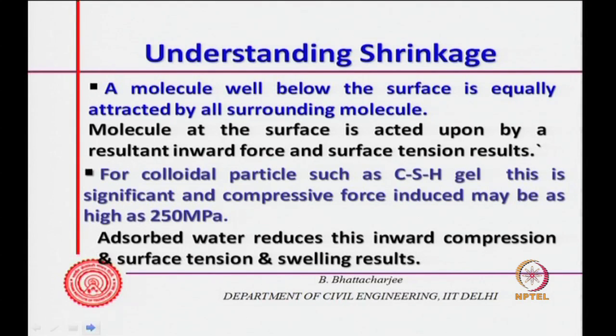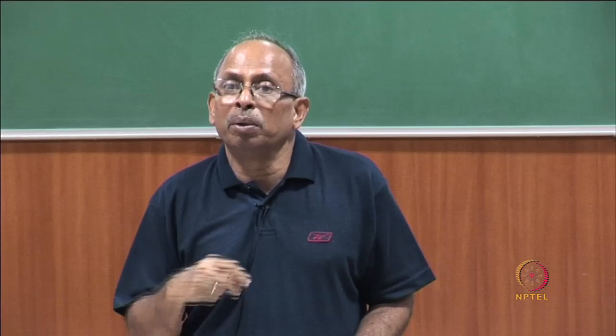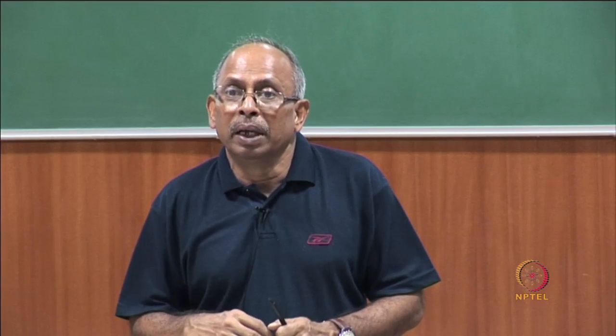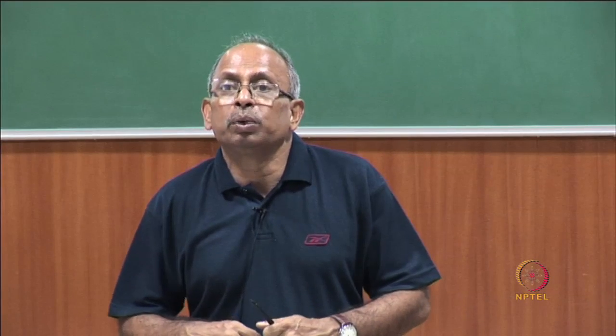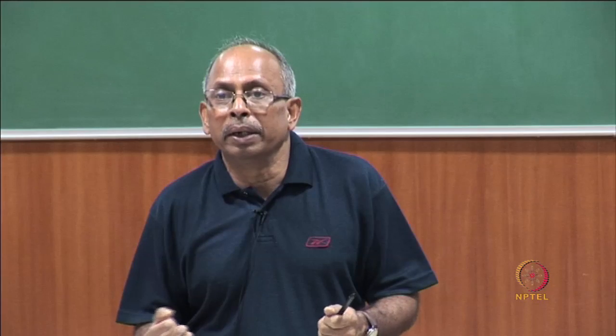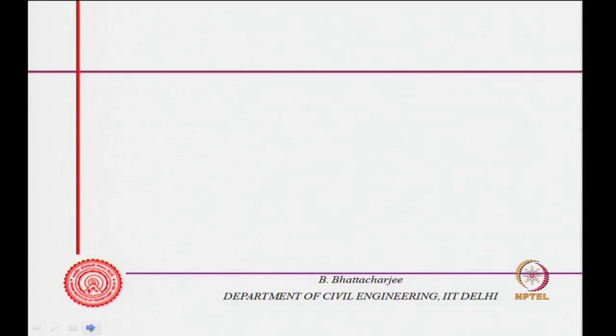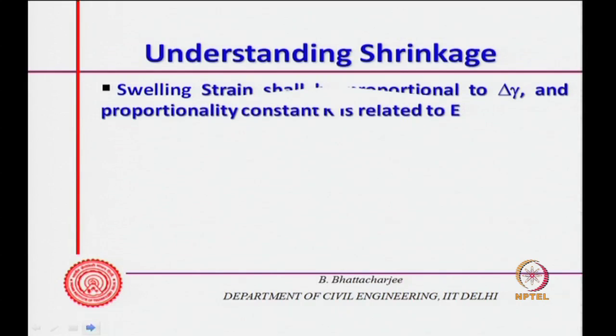If there is no adsorbed water, then the molecules of the C-S-H particle system will pull the surface ones inside, and it would induce a kind of compressive force. Now, if there is adsorbed water, this compressive force will get reduced. In other words, surface tension would reduce and swelling will result. So, adsorption of molecules results in swelling, and swelling strain is proportional to the surface tension itself.